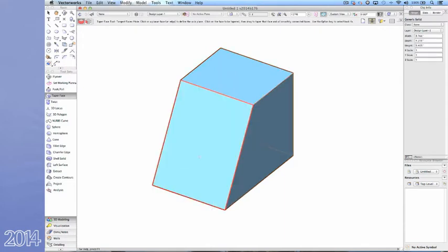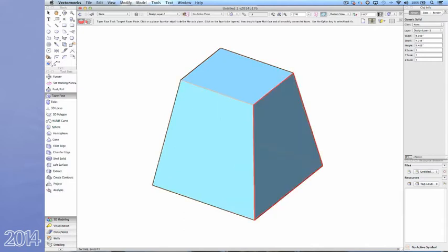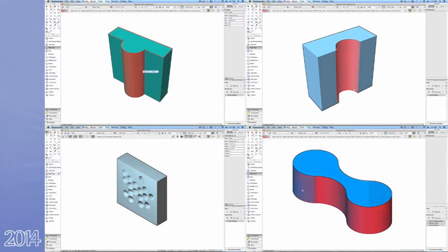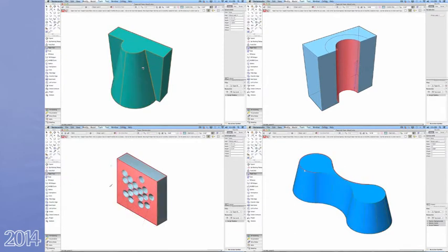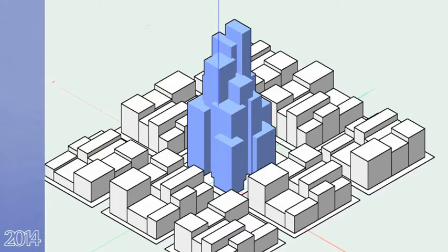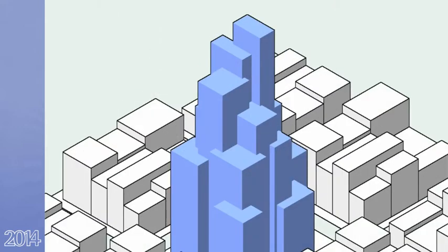The new widget will preview the direction. Then simply drag and release. For a precise angle, you can input values into the heads-up display. Taper Face can be used to widen the base of solids and make tops narrow, and lets you get very creative when modifying solid subtractions. In its simplest form, the tool will help you explore new design ideas by deforming solid objects.